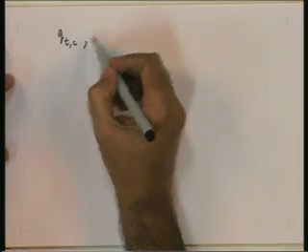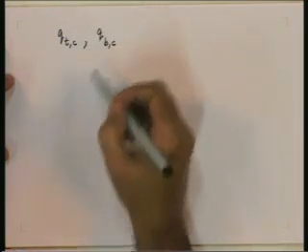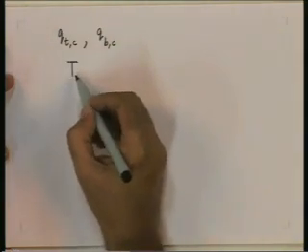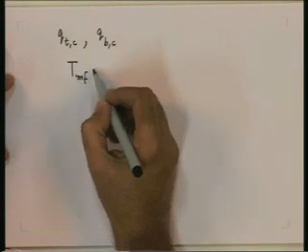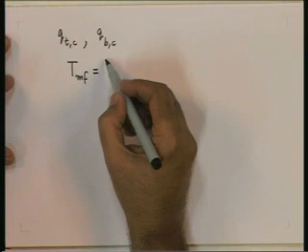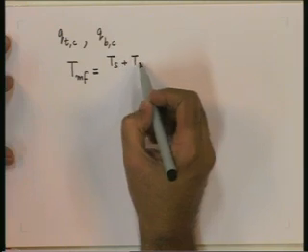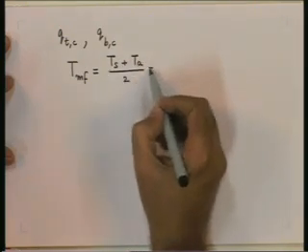After having completed the task of obtaining the radiative components from the top surface and from the bottom surface, let us move on to compute Q top by convection and Q bottom by convection. For this, we will have to calculate Rayleigh number, and for calculating that we need properties at the mean film temperature, which is T surface plus T air divided by 2.